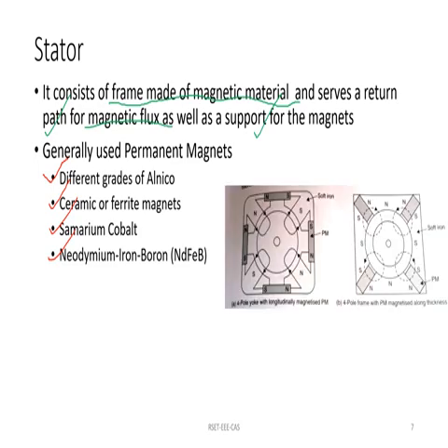Now these two figures are the examples of a four-pole system. The first figure is a four-pole yoke system with longitudinally magnetized permanent magnet. So here we are using 4 poles, 4 permanent magnets, 1, 2, 3, and 4, and a soft core material adjacent to these will also get magnetized with south pole.